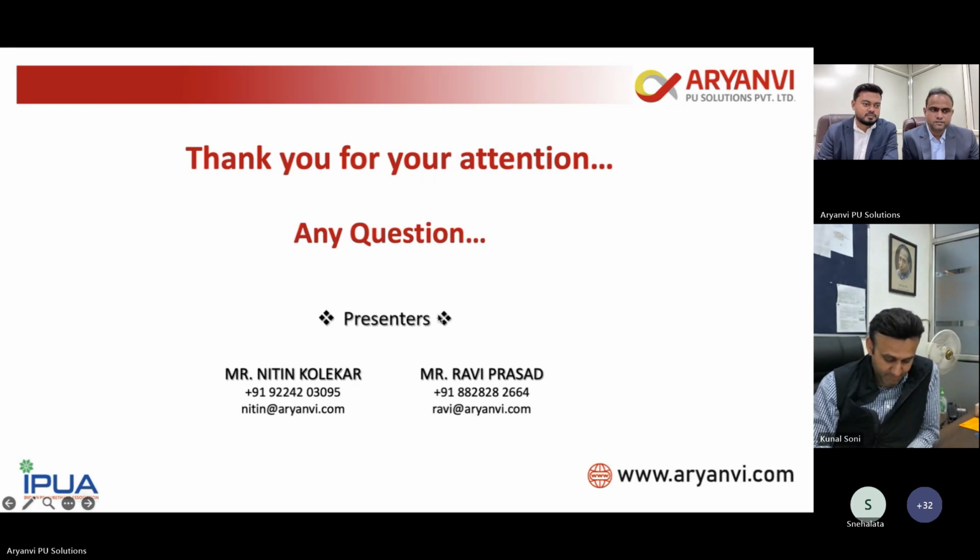Thank you, Mr. Ravi. But is there a risk in terms of safety? If you use water and there is a jacket failure, or the shell or heat exchanger gets damaged, there have been incidents where isocyanate, MDI or TDI mixed with the water, and there was complete damage of pumps and all the critical items.